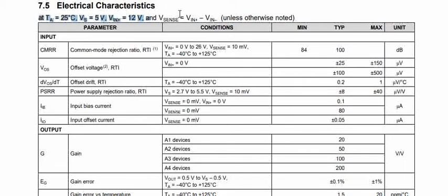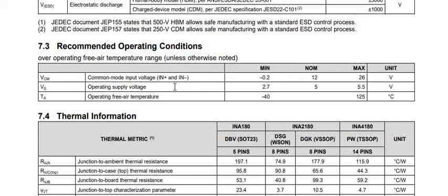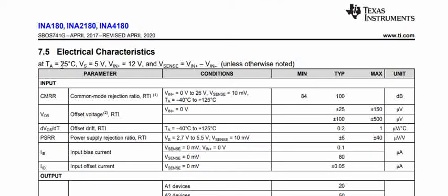So considering these parameters, the op amp is characterized, that means the specifications below are done only with these parameters. No other conditions are considered. Like for example, if you see this INA215 data sheet, it supports up to 125 degrees centigrade actually. Now the actual electrical characteristics are mentioned at 25 degrees centigrade. So most of the design engineers do tend to miss out on this particular condition, and just check the specifications directly.